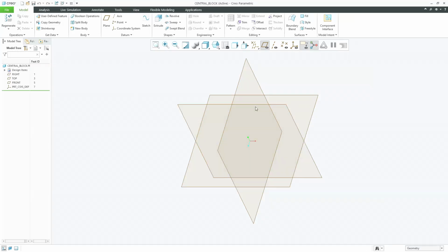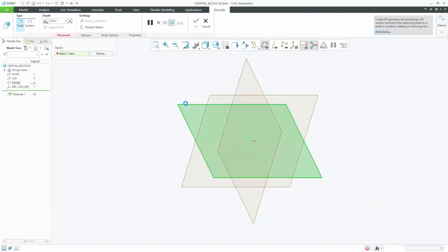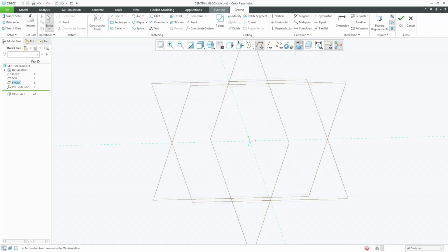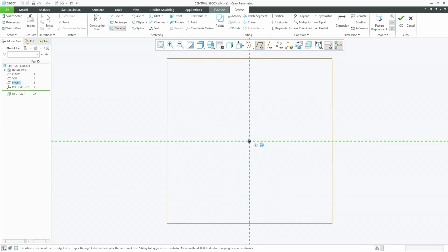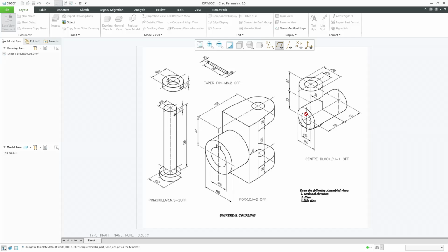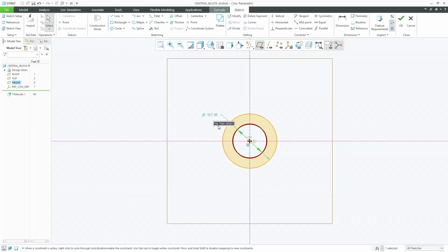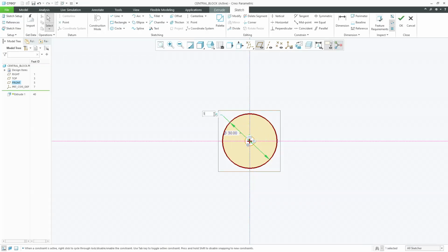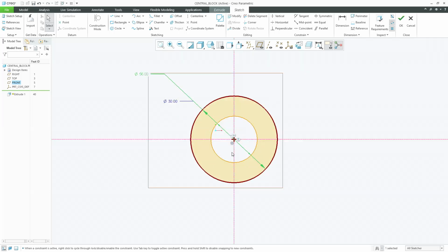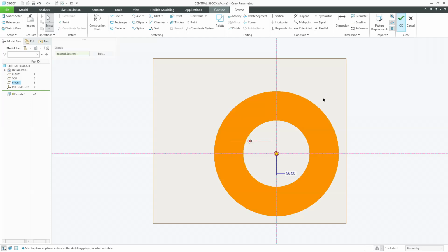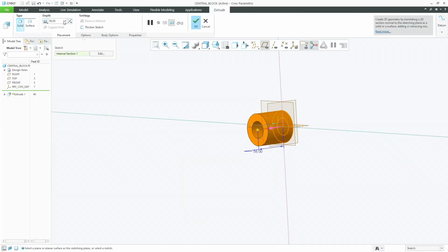So first I'm going to select the front plane surface. I'm going to select the circle command and draw two circles, and I have also forgotten to add the center lines. Let me add them. The diameter of the shaft should be 30 and 56. The inner diameter is 30, our external diameter is 56, and this should have a symmetry of the distances 53 on both ends.